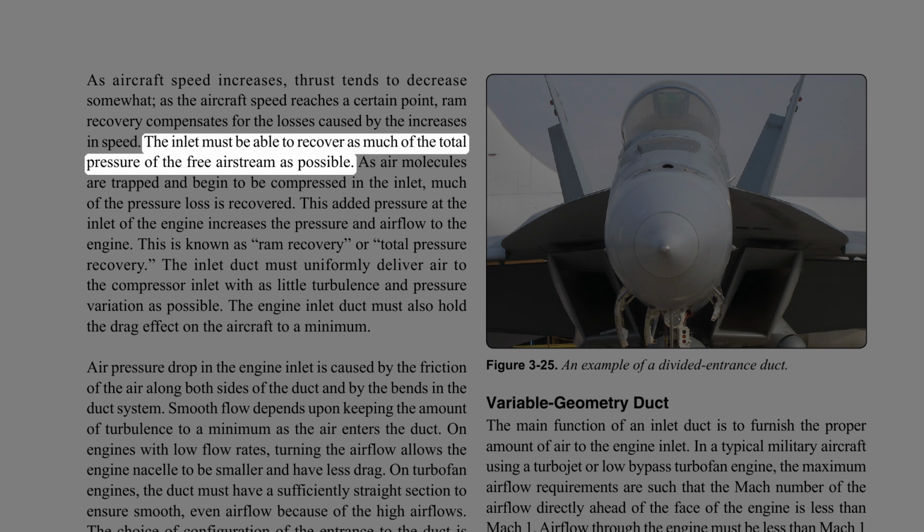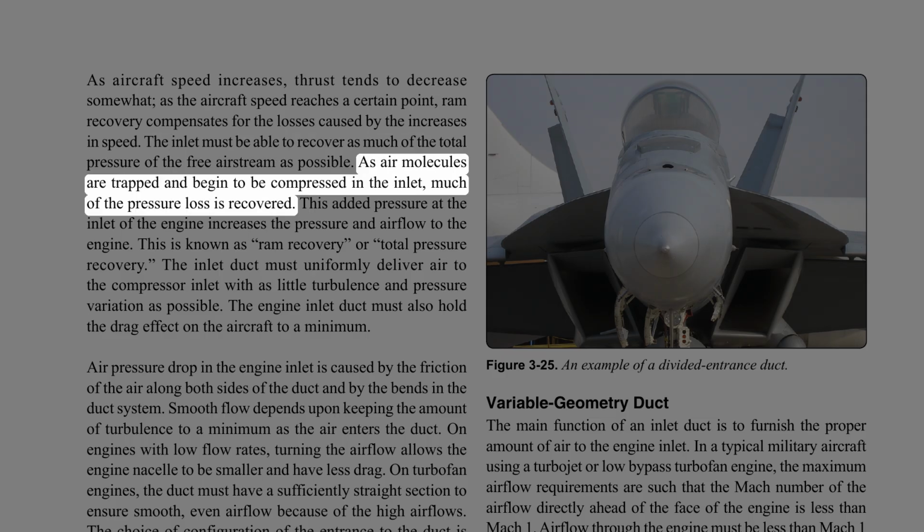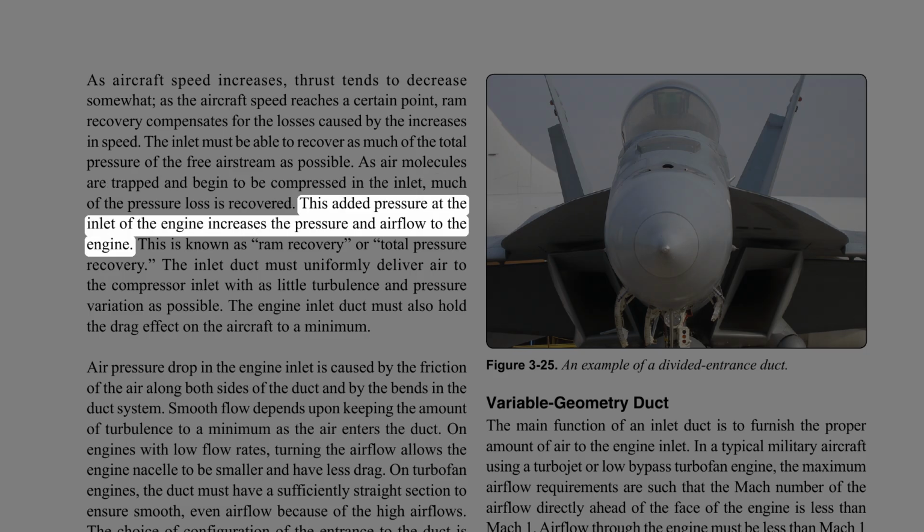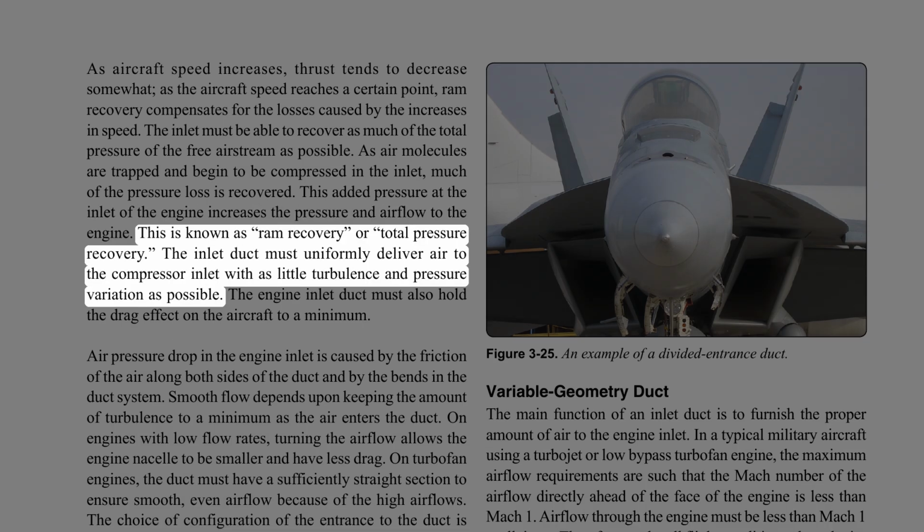The inlet must be able to recover as much of the total pressure of the free airstream as possible. As air molecules are trapped and begin to be compressed in the inlet, much of the pressure loss is recovered. This added pressure at the inlet of the engine increases the pressure and airflow to the engine. This is known as ram recovery or total pressure recovery.